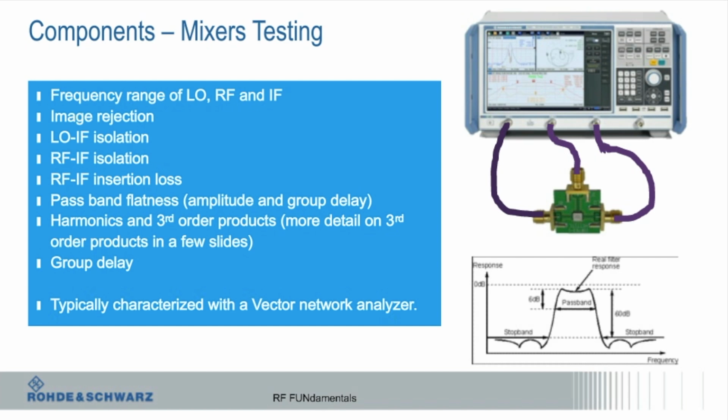So when you figure out what frequencies to use, you need to be really mindful of what frequencies you're picking, particularly for the LO, because that's usually the one you get to pick. Usually the RF is defined by the standard. If I'm doing cellular, the standard says I'm at 700 meg. It's an LTE phone, so it's a 700 meg RF. My A to D is at 70 megahertz.